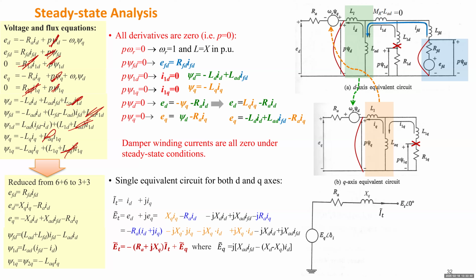So if you took 421 or any other power system analysis course for static conditions, you might have learned this equivalent circuit. In that equivalent circuit, usually for the reactance, we use a notation which is XS. We call it a steady state reactance. From this circuit now, you know that reactance has to be XQ, so it's not XD, it has to be XQ. For a round rotor generator, maybe XQ and XD will be very close, so you can use either one.